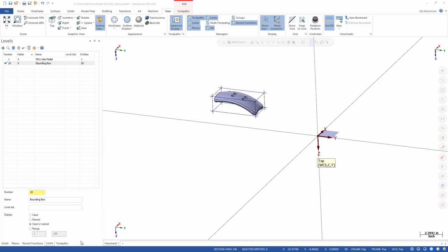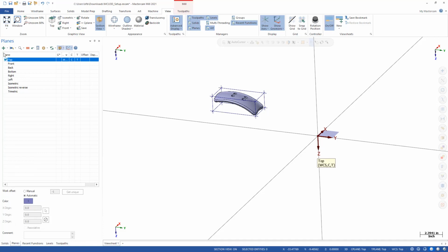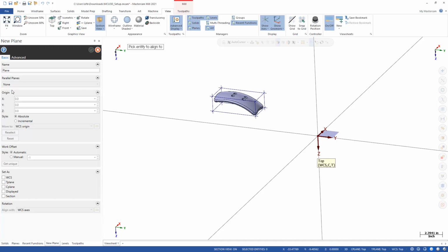So at this point, let's go and create a new plane by clicking on the Planes tab. Then under Planes, we see we have a plus here, and we have a variety of options for various methods for creating planes. I'm going to use Dynamic. What Dynamic lets me do is snap my geometry, or in this case my gnomon, somewhere on my geometry to lock that plane in place. And even before I locate this plane, I can go up to the Name section and create a new name for this plane. So this plane will be called Op1.